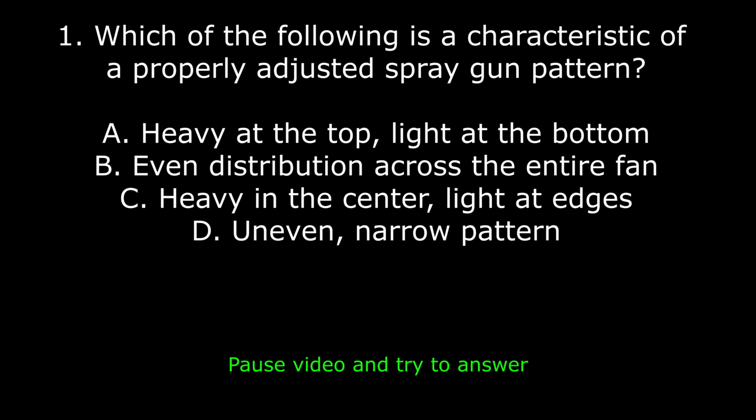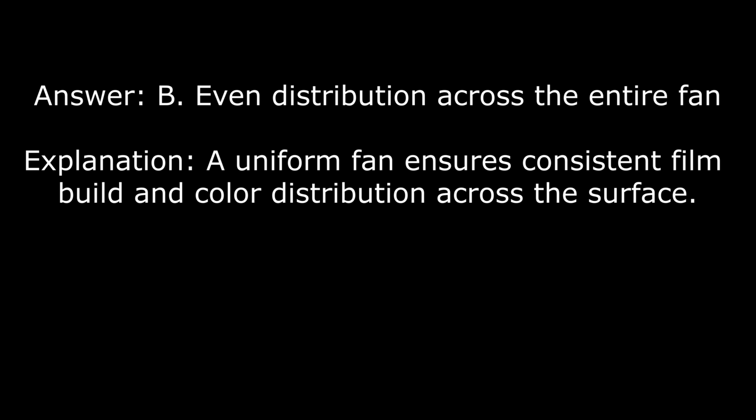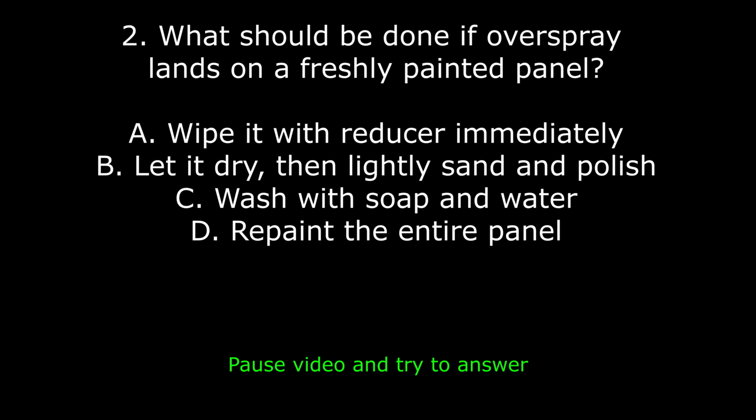Which of the following is a characteristic of a properly adjusted spray gun pattern? A. Heavy at the top, light at the bottom. B. Even distribution across the entire fan. C. Heavy in the center, light at edges. D. Uneven, narrow pattern. Answer: B. Even distribution across the entire fan. Explanation: a uniform fan ensures consistent film build and color distribution across the surface.